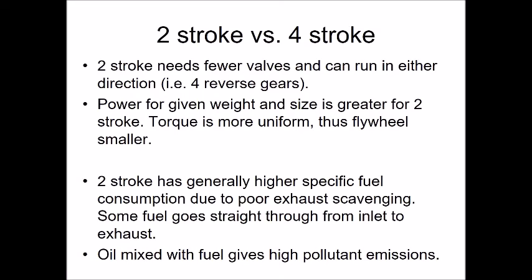So a 2-stroke cycle needs fewer valves. So go back to the diagram and the video, and you'll realize that in many cases you can almost get away with no valves at all. What you actually need is a hole in the side of the cylinder, and the piston head itself actually forms part of the sealing of the process. So it's quite good in that respect. And it can actually run in any direction. So something to do if you're ever that way inclined. You can sometimes get hold of 2-stroke engines for running things like golf carts.